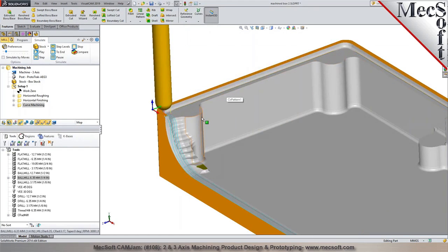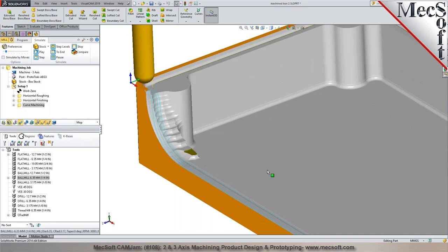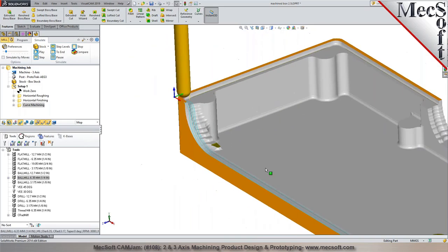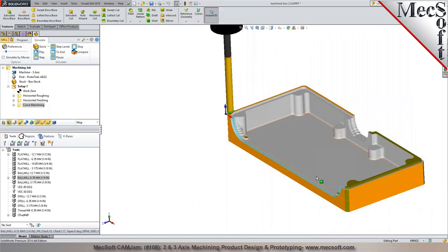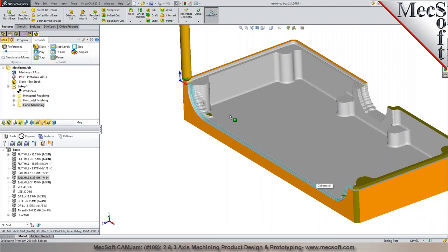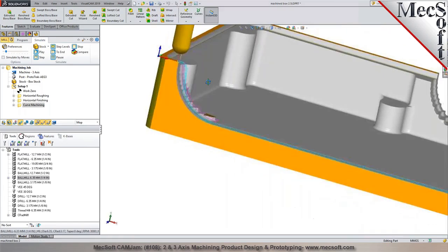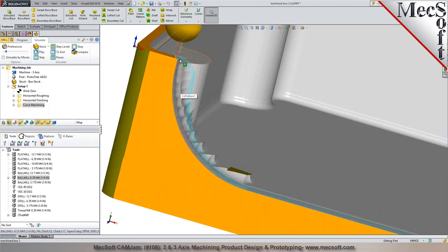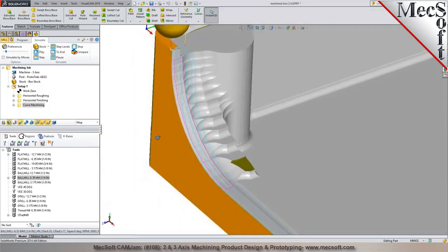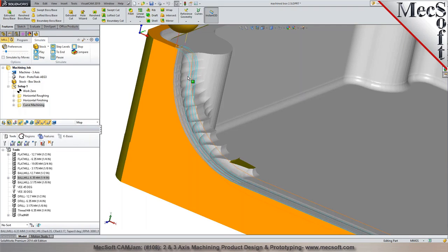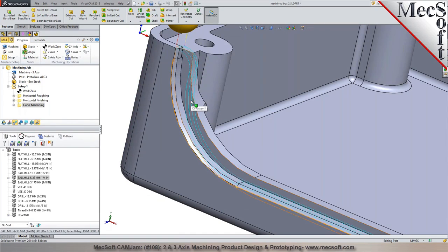So these are some of the advanced 3-axis capabilities that you have in the Pro, where you can determine what type of toolpaths you would like to accomplish or generate. Now, to try to do this in the 2D programming paths, it would be fairly difficult, correct? Well, you can't really do a 2D operation unless you flip the part and machine it with the side of the cutter like a profile. You put it on the side. Yep. Because over here, if you're doing a 3D cut, the tool tip is what you display in the toolpath here. So it automatically compensates for the tool based on the geometry that you're following.